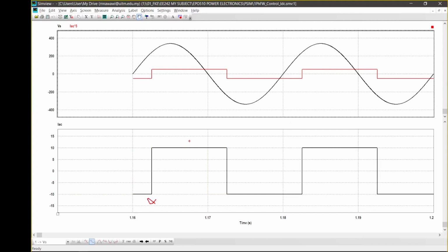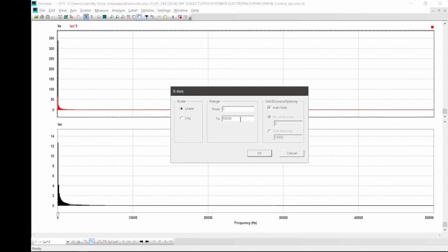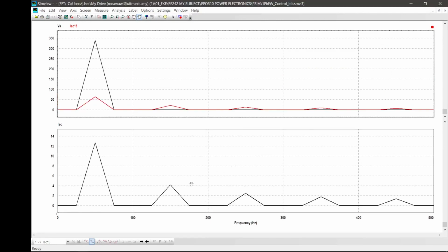Okay, and if I use the fast Fourier transform, click that, and if I look at the square waveform again, it is very similar to what we had before, which means you have the same C1, C3, C5 and the rest. So there is no difference between controlled and uncontrolled rectifier, between the square waveform that starts at 0 or the square waveform that starts at alpha. No problem with the magnitude. So you have the same C1, C3, C5, the rest.